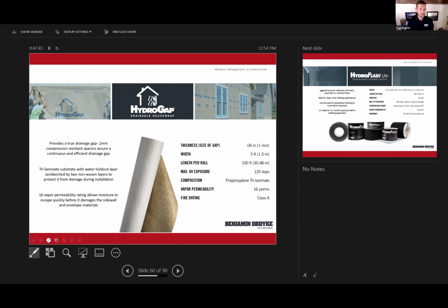Really nice, smooth, easy product to use. Put it up with a cap fastener, 5, 9, and 10-foot widths. Contractors love the 5-foot width. It's so easy to work with in the field. One guy can do it. This can be installed any direction. Of course, in the pictures, we like to show the logo and the writing right side up. You can install it upside down, up and down, diagonal, doesn't matter. It's going to work. This is a good, strong, durable house wrap.